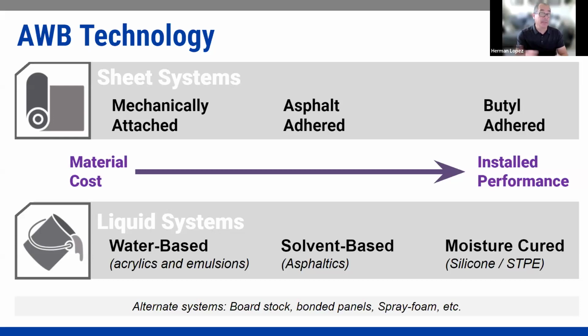away from the system, potentially going inside of the structure. But along with that, the other thing is at the critical junctures, the transitions to doors and windows, seams, corners, and whatnot. That shrinkage can potentially cause some cracking, and those critical interfaces are the most vulnerable if you were to throw a crack in there. Prior to that, we had water-based.